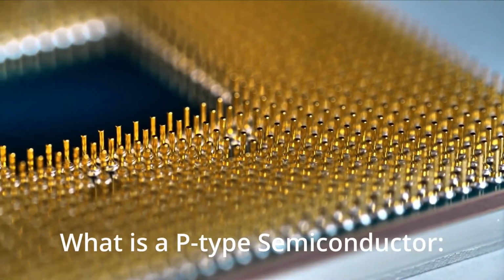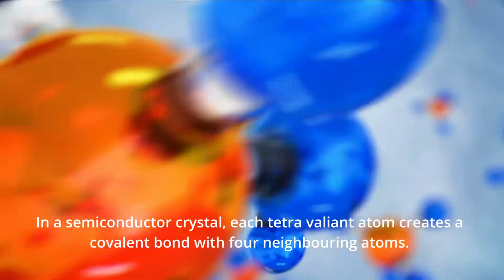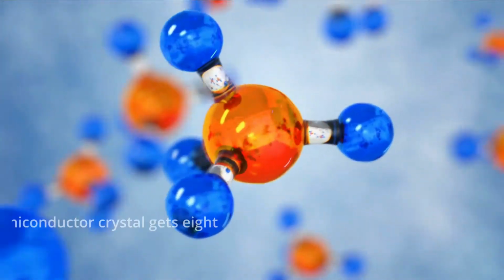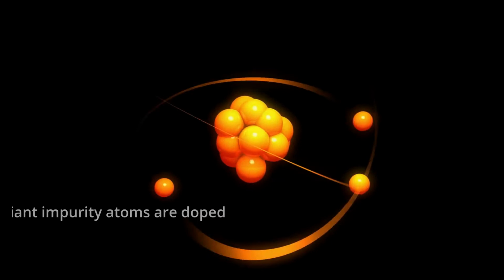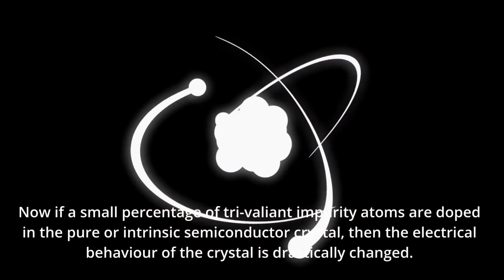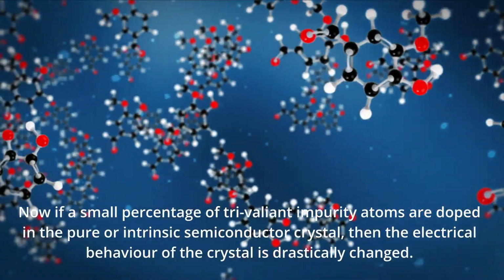What is a P-type semiconductor? In a semiconductor crystal, each tetravalent atom creates a covalent bond with four neighboring atoms. In this way, each of the atoms in a semiconductor crystal gets 8 electrons in the outermost orbit. Now, if a small percentage of trivalent impurity atoms are doped in the pure or intrinsic semiconductor crystal, then the electrical behavior of the crystal is drastically changed.